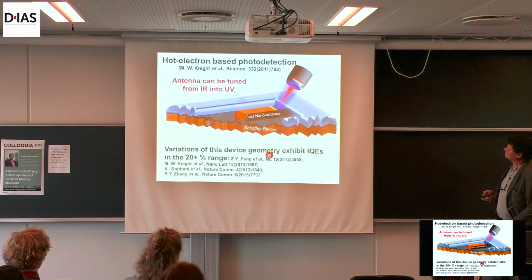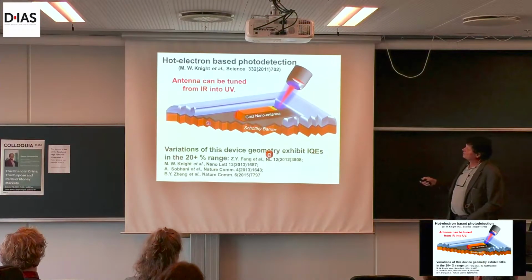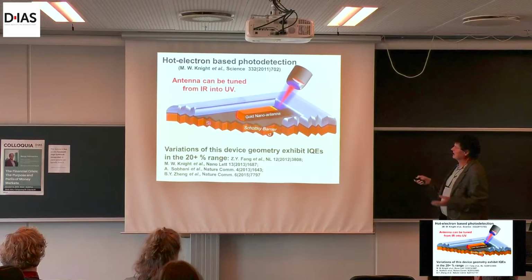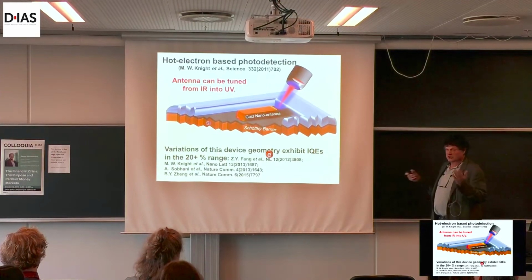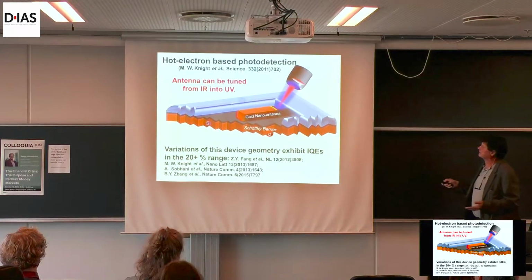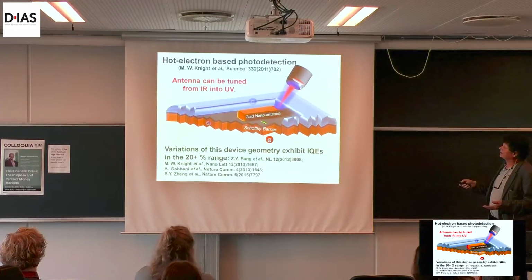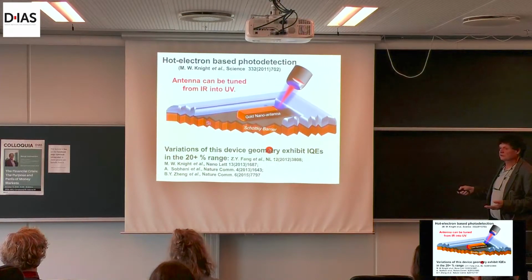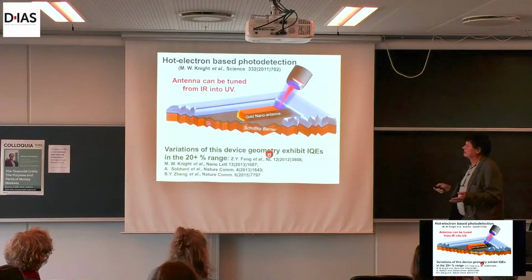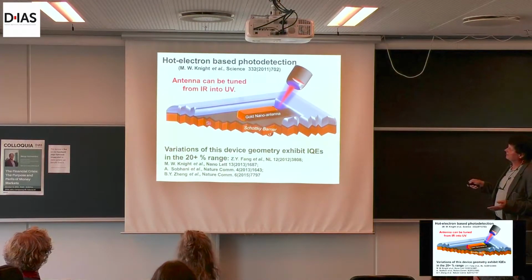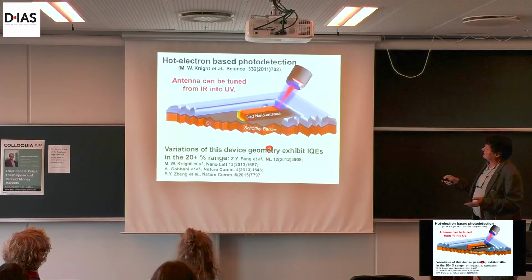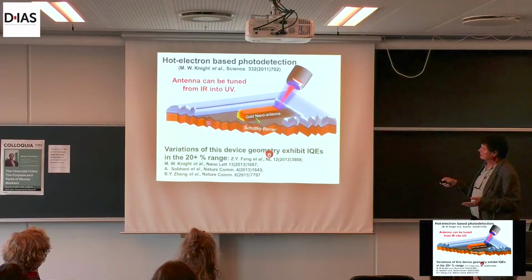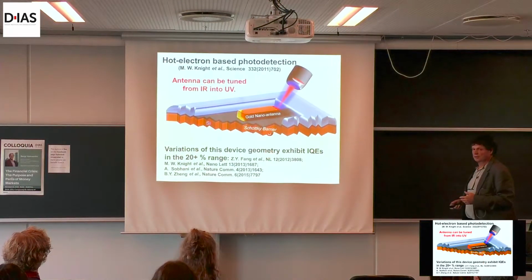Photodetection, okay. This was the first paper. So we put a plasmonic nanoparticle on the silicon device, and when we now excite the plasmon, and the color here we tune by changing the shape of the nanoparticle, that's not interesting. When we excite light, we are generating hot electrons who can go into the substrate. You can detect them as a current. This device has to be covered by something conducting and transparent because if you didn't have sort of a backflow of electrons here, you would charge the particle and you would stop, okay?